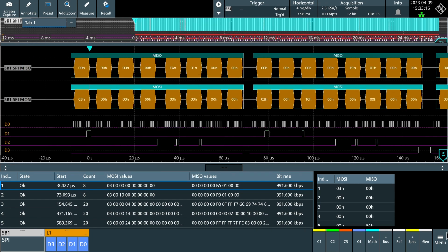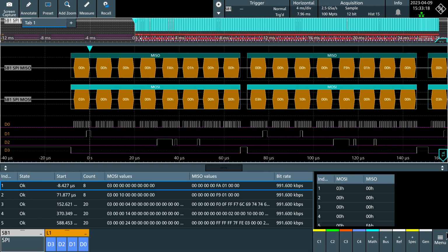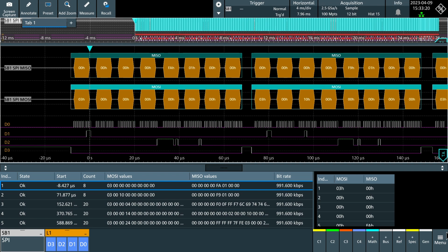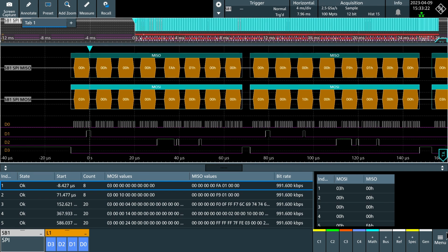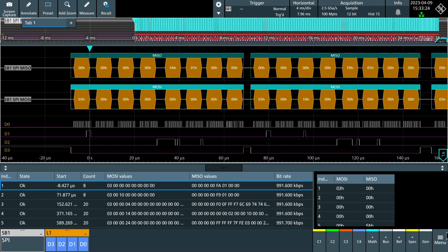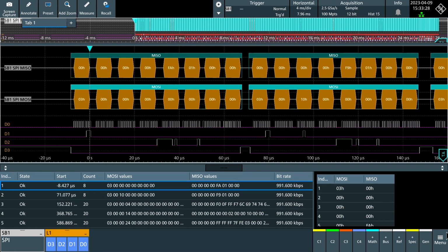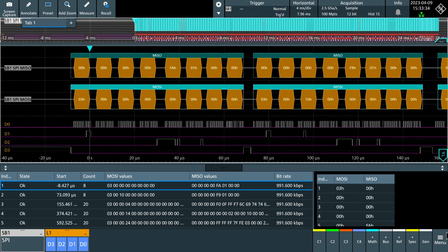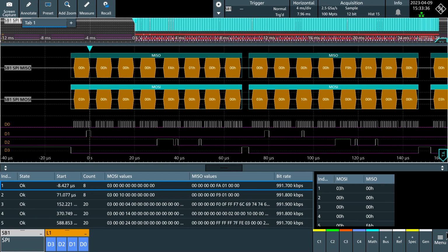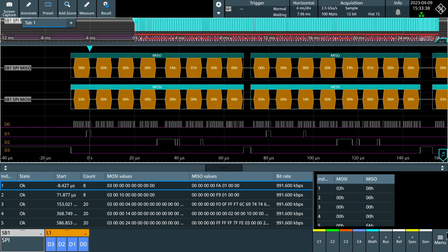This sort of display is very quick to create because of a feature called dual path. What it does is that it automatically ensures that the capture is done with enough granularity for the protocol to be decoded, leaving the user to concentrate on the protocol troubleshooting rather than on the scope setup. The large display allows quite a lot of data bytes to be read directly off the zoom view, and it gracefully adjusts if the amount of zoom is changed.